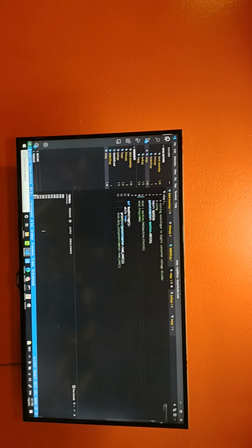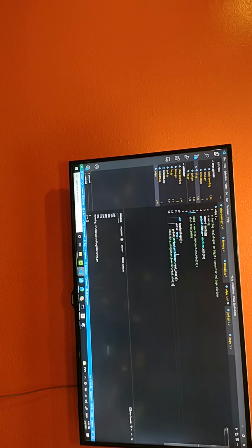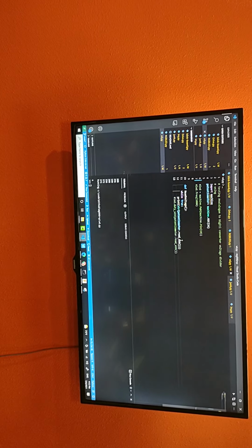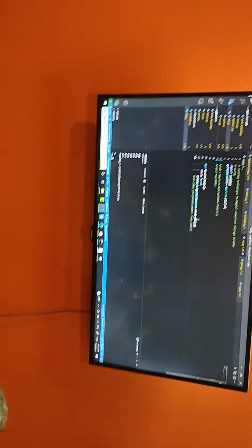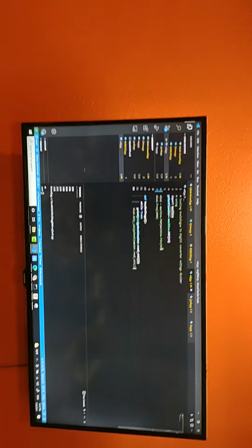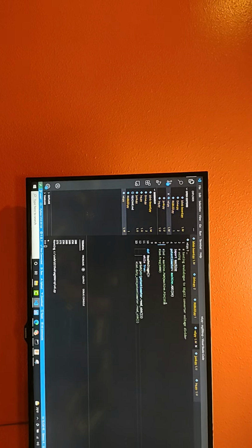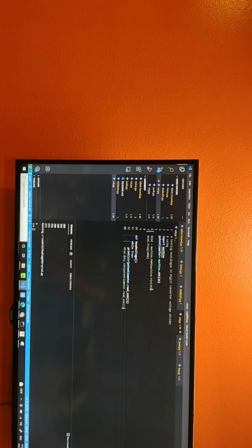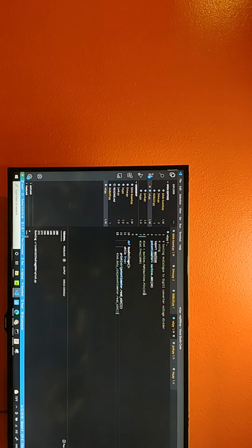All right, let's stop this. That's pretty cool, that it reads that analog signal. So now we're going to use that value, 0 to 65,000, to set up our PWM onto pin 19, the same pin that we were using before. We're going to adjust what percent of time it's at the 3 volts versus the 0 volts, so we should be able to change the brightness.